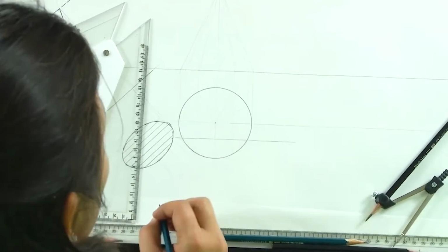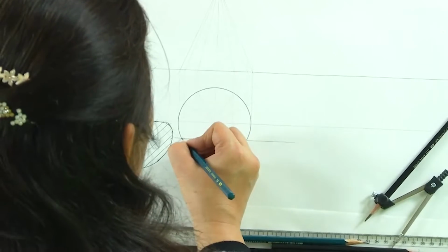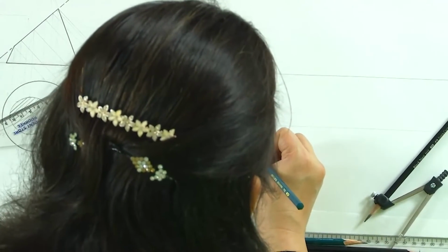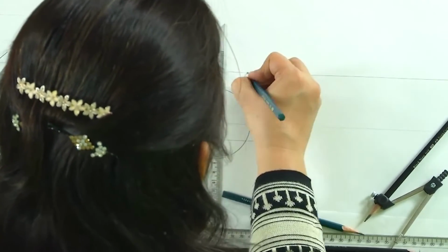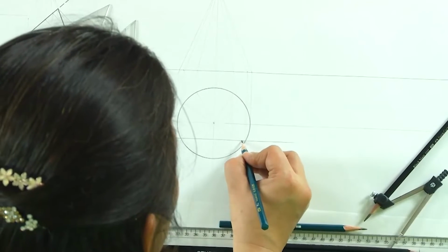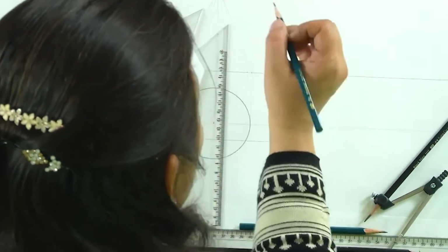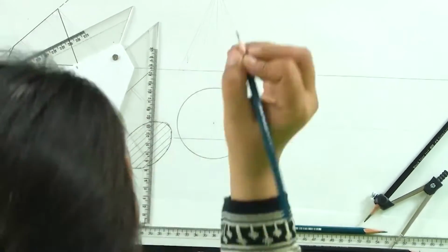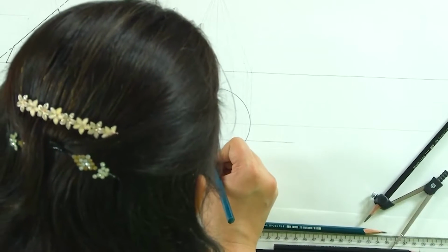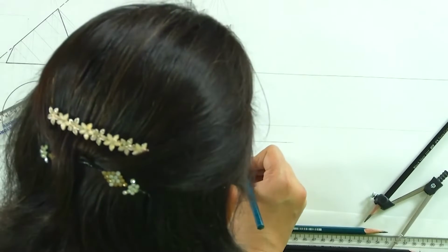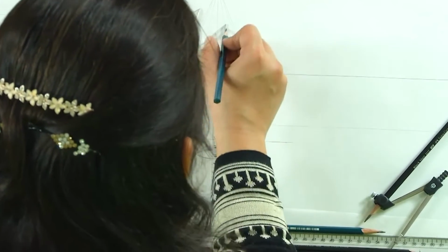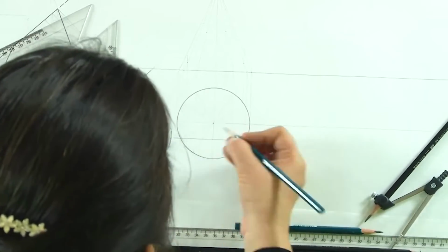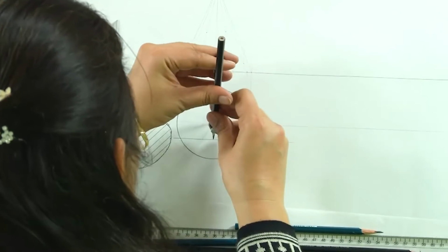Now let us see where each of these generators is going to be intersected. So what we see in the base, this is the point where the section plane is going to cut. So this is where the section plane in the base is going to be. Now this generator is getting intersected in this point. So if I make it like this, these are the 2 points I get. Now the next generator is this. So we get 2 points here, and again the same for this one. We will take it, this is going to remain at the same distance.